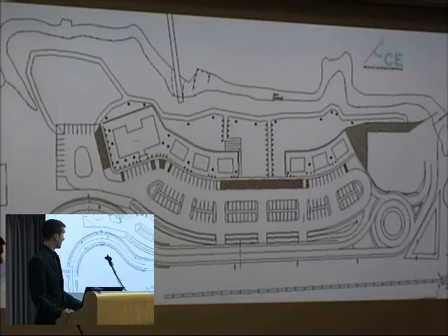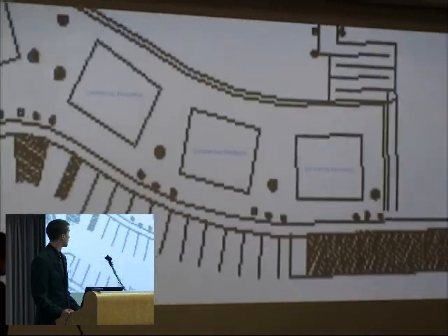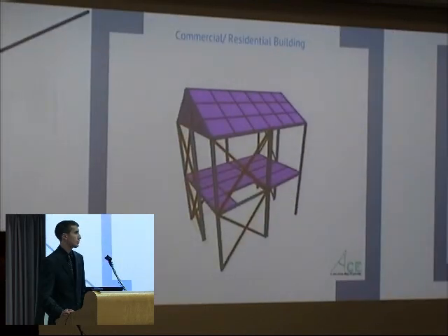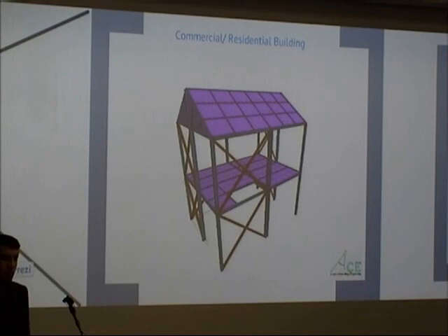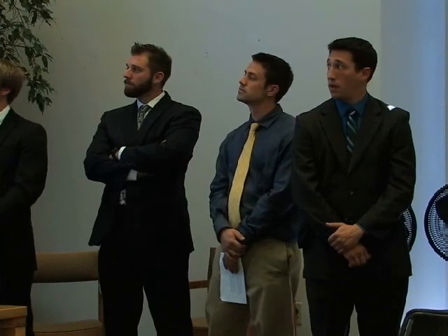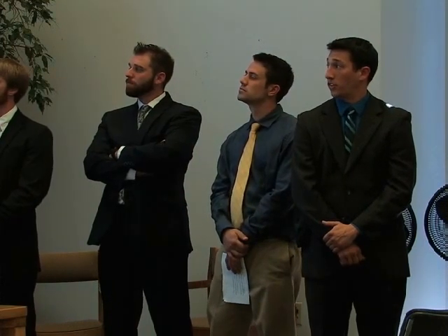I will now bring Chris back to talk about the retail. Yeah, so we spoke about the 3 major retail and residential buildings that we are having for immediate construction. Displayed here is another 3D rendering that was performed in STAAD. You can see the cross bracing on the sides that weren't crucial to have windows, and where windows were necessary, where the seaside view was important, we used moment connections.